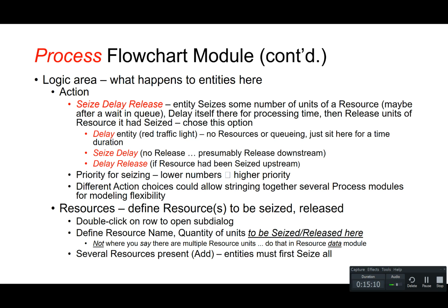For resources, define the resources to be seized and released by double-clicking on a row to open the dialog box, defining the resource names and the quantity of units to be seized and released here. Several resources can be present, and you must first seize all.